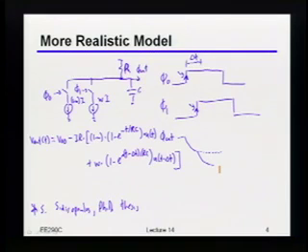And by the way, the reason for doing this is that now, if we actually look at what is delta t, and you can imagine you're always going to normalize that delta t to RC, right? Because it's really just those relative times that matter. Now what we can do is look at what happens as we change that RC relative to the delta t, right? As an example, if the RC is very, very small, that implies that we're going to have very, very sharp edges at the output. And if the RC is large, then that's going to imply that we're smoothing things out more, right?